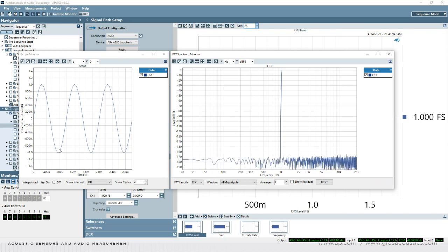What Audio Precision has decided to do is when we describe the instantaneous value of a digital signal, we use a different unit, D. So where with volts, we have a subtext which tells us whether it's an instantaneous or RMS value, with FS, FS means RMS, and in the context of an Audio Precision analyzer, D means instantaneous digital level.